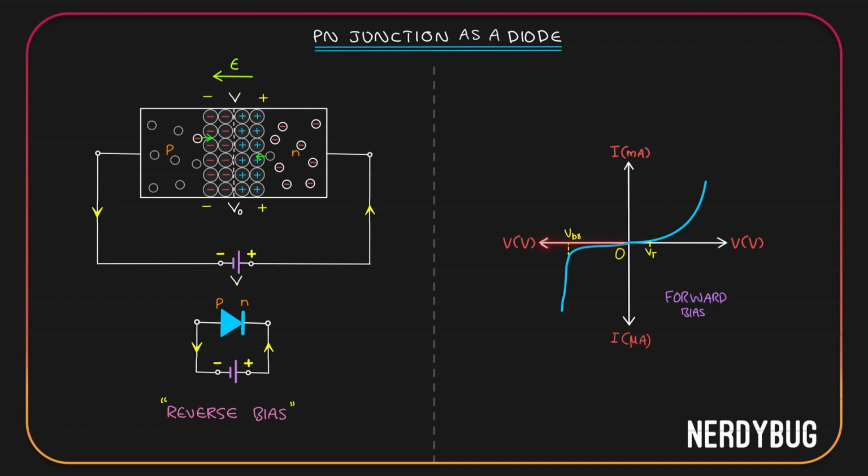When the applied voltage is negative, the current is almost constant for a long time. That is because the reverse bias current mainly depends on the availability of the carriers. Even if you increase the applied voltage, it is not going to have any effect on it. So we get the constant current until the applied voltage reaches the breakdown voltage VBR, after which the diode gets damaged and the current increases sharply. Now under reverse bias, the current is in microamperes. So on the negative y-axis, we have taken I to be in microamperes.